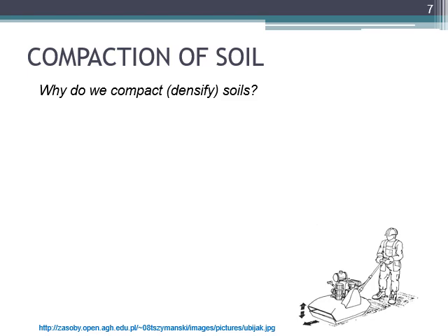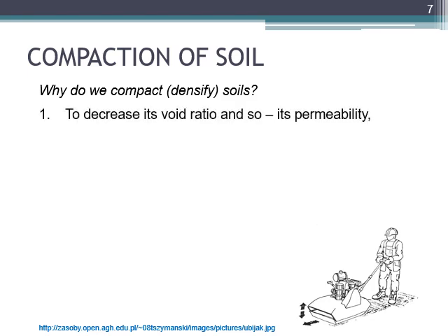Now, why do we compact the soil? Why do we want it to be dense? What do you think? Well, first of all, we want to decrease its void ratio, and so also its permeability.